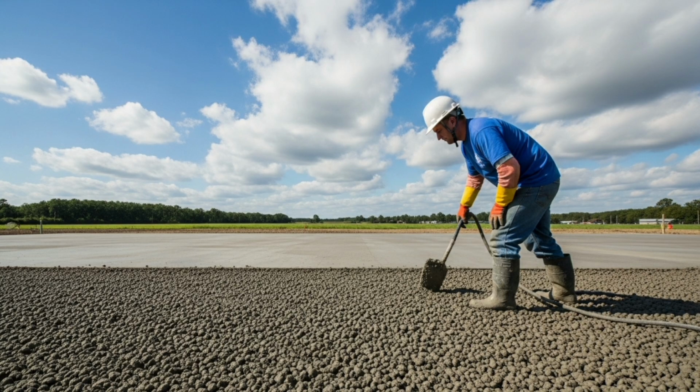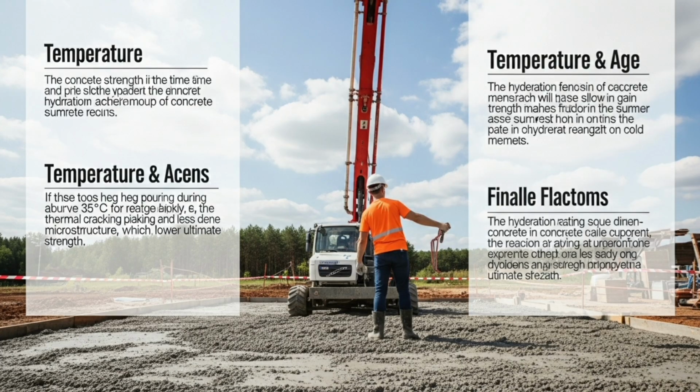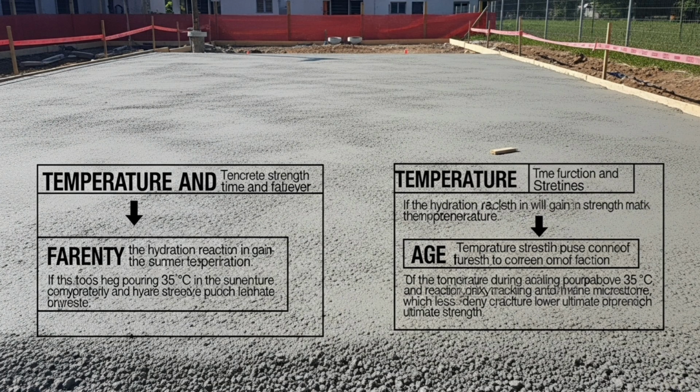Third, the gradation we discussed in the previous video is critical. A well-graded aggregate pack with minimal voids requires less cement paste to fill the gaps, allowing you to use a lower w/c ratio for the same workability, which directly boosts strength.